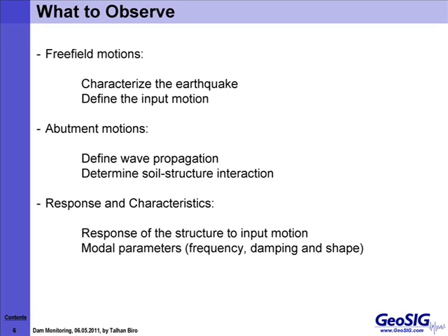So based on this information, we need to understand what we need to observe in dams, because we are here to understand what to observe in terms of the earthquakes that are acting and exerting forces on the dams. First of all, we have to look at free field motions. Free field, as you might remember from my previous slide, is the point that is far enough away from the dam structure itself so that the structure's movements are not affecting it. Using these free field motions, we can characterize the earthquake affecting the dam or the area.